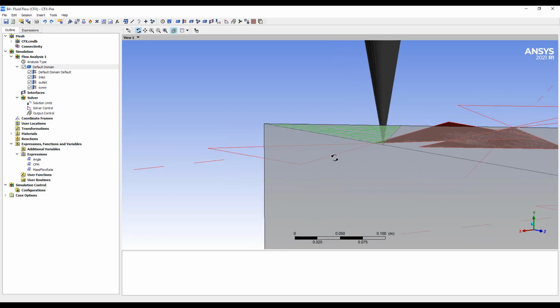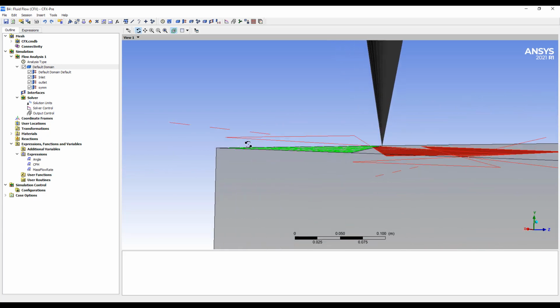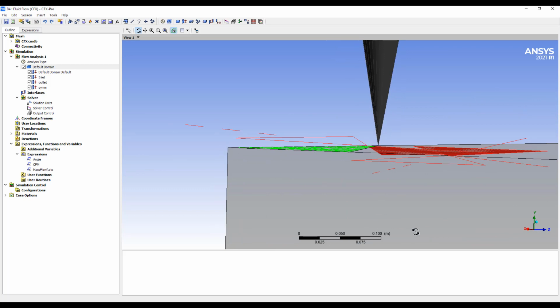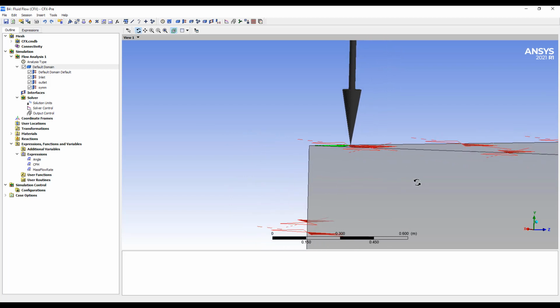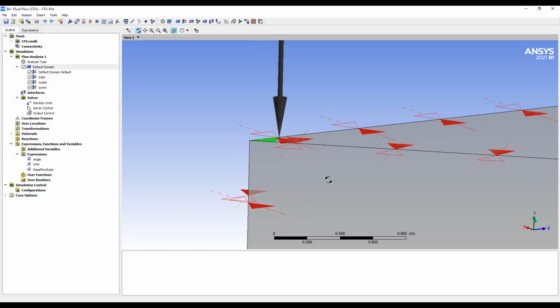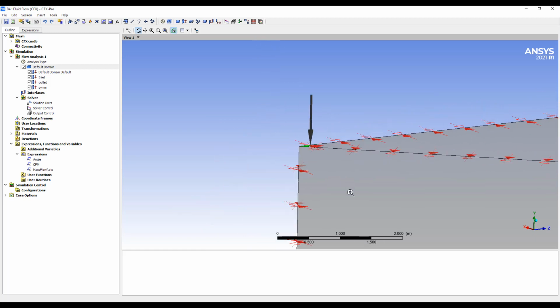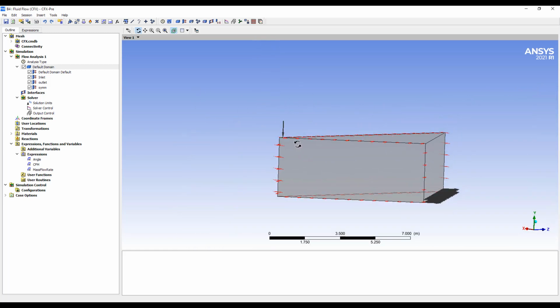So this will create a flow that will come out at 60 degrees. If we see 45 degrees as directly diagonal, 60 degrees is a little bit more towards the wall. And that's oftentimes the way diffusers work. They shoot the air along the wall, have the jet go around the wall, and then cause circulation inside of the room.